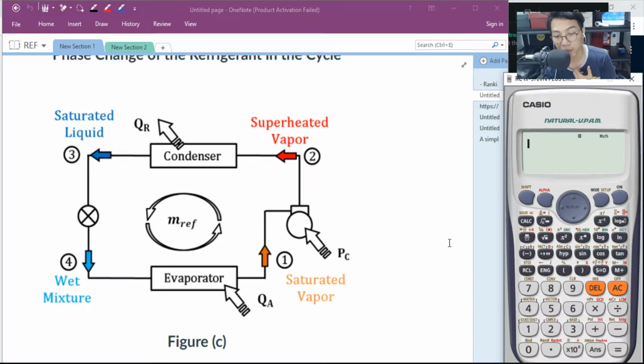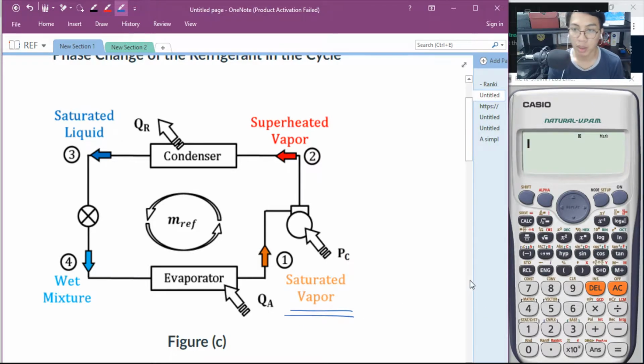And then, your refrigerant, before entering your compressor, is in the state of a saturated vapor. So, if we compare it to water or steam, it has its own table. Okay? You're done with thermo already, right? So, in chart reading, let's say this is water, okay? Or steam or vapor. When it is saturated vapor, where would you look in your steam table? Of course, in the saturated tables, where at saturation pressures and temperatures, there are two of those tables. Tables 1 and 2 when you are looking at your steam tables.